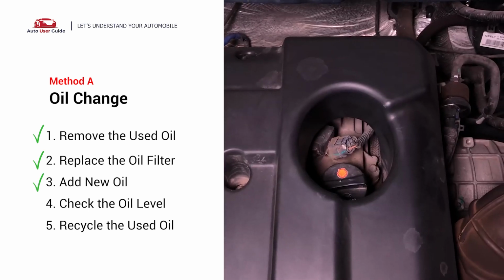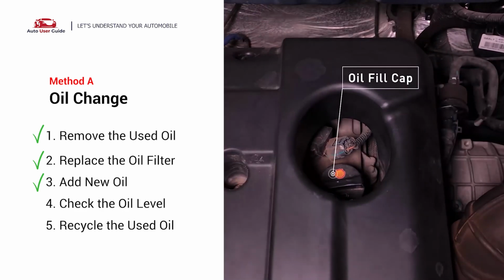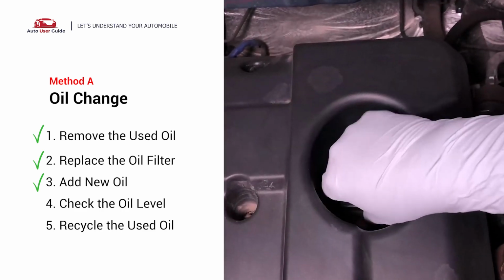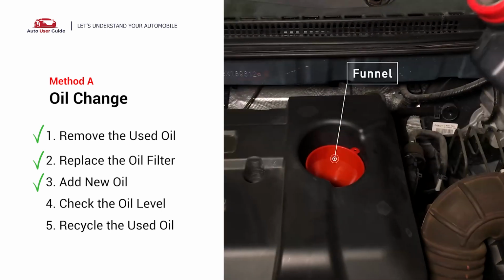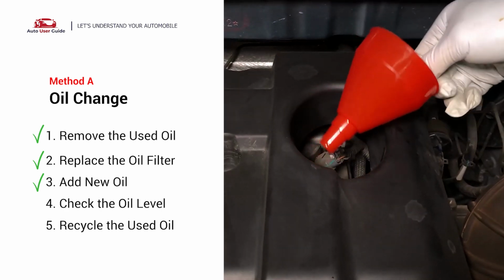To fill the vehicle with fresh oil, you should first locate your oil fill cap at the top of the engine. Clean the cap before removing it. Take the cap off and place the funnel into the opening. Add the amount of oil specified for your vehicle, and then replace the cap.